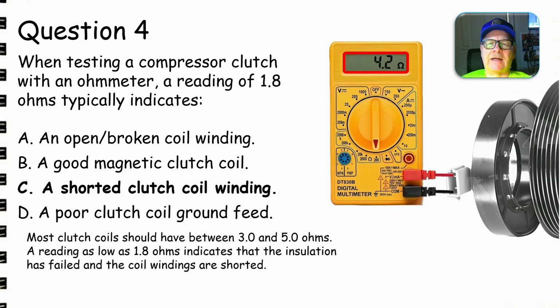he says, I'm going to have to take the wire harness completely out from under the hood here, you know, the one that's affected, which basically the whole thing, and I'm going to have to split the tape off of it, and I'm going to have to fix every wire individually. And I can do that, but you're going to pay me my shop rate for as long as it takes me to do that, because I don't have a fixed rate for fixing a wire harness that's burned up like this, and especially since you can't just replace a wire harness.